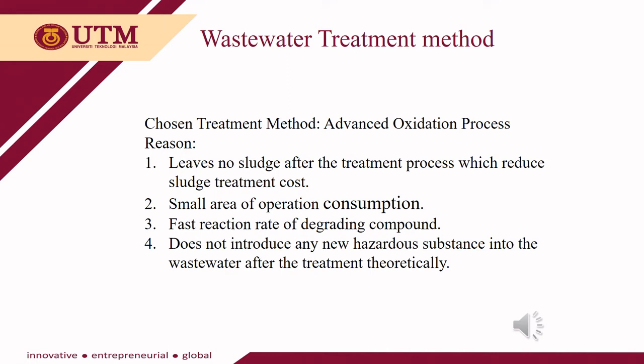The reason we chose the advanced oxidation process is because it leaves no sludge after the treatment process, which reduces the sludge treatment cost. Besides, the advanced oxidation process also requires a small operating area, has a fast reaction rate in degrading compounds, and theoretically does not introduce any new hazardous substance into the wastewater after the treatment.